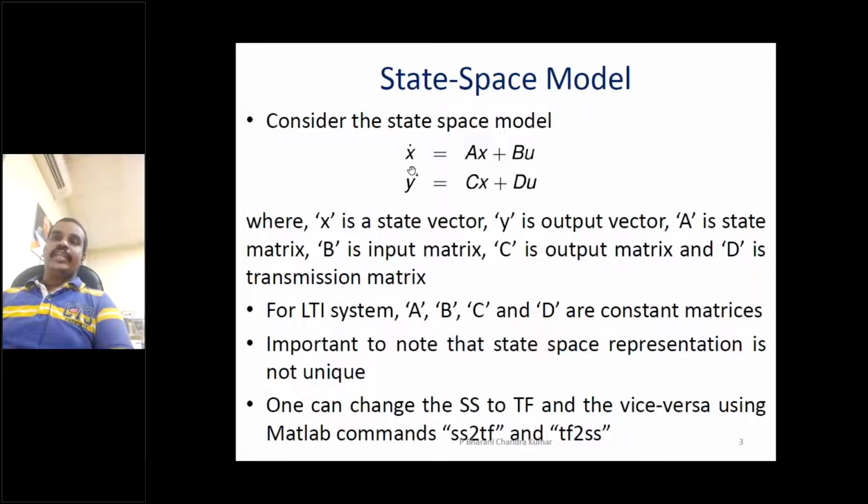If you consider some of the states as a constant, which are not varying with respect to time, let us assume R, L. If it is not varying with respect to time, and you take the derivative of that particular constant, it will become zero and it is useless. You cannot do anything. So that's why the states, whatever you are considering, should vary with respect to time. For example, the currents, voltages, speed, and those kinds of elements one can consider as the states.